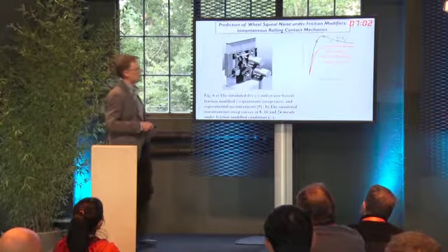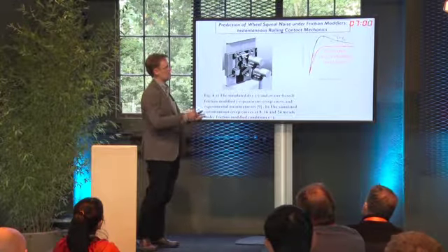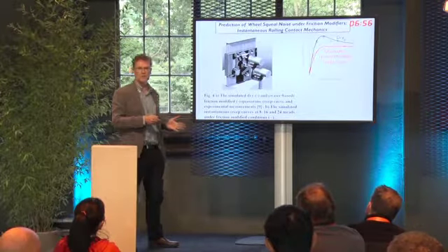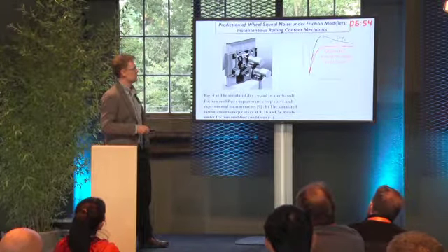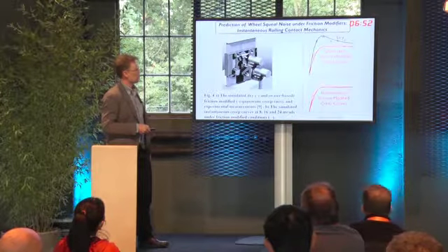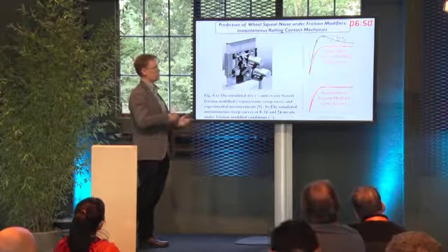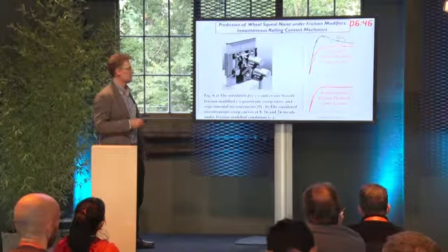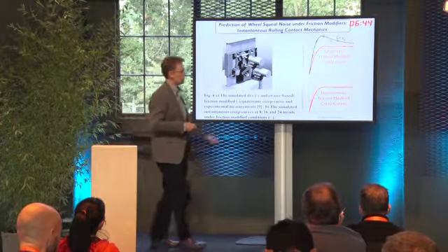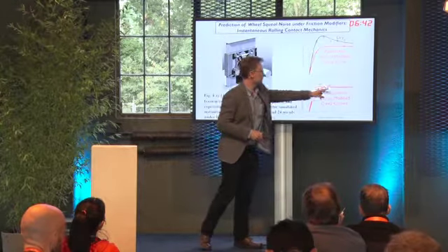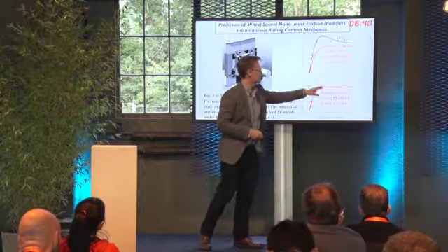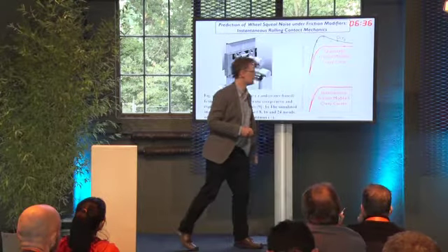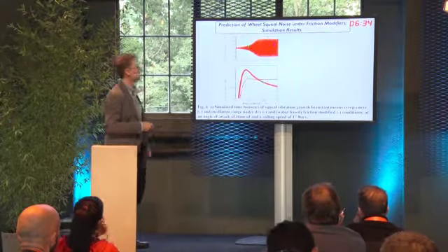So what that means is when we do a measurement of the creep curve, we're just measuring the quasi-static creep. But what we can do is back infer what the instantaneous creep curve would be. For each point on the quasi-static curve, you've got an oscillation that occurs instantaneously, but averages out to the same point on the creep curve.